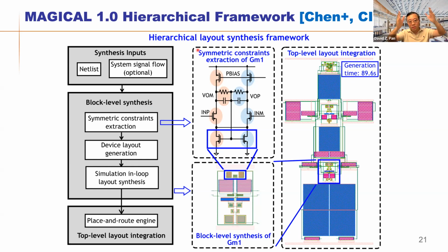So in that sense, we can do hierarchical layout synthesis. If you have a very big design, you just decompose it into different hierarchical levels, and then you gradually move down to the lowest level, finish that first, and then you gradually build up the entire top level layout.